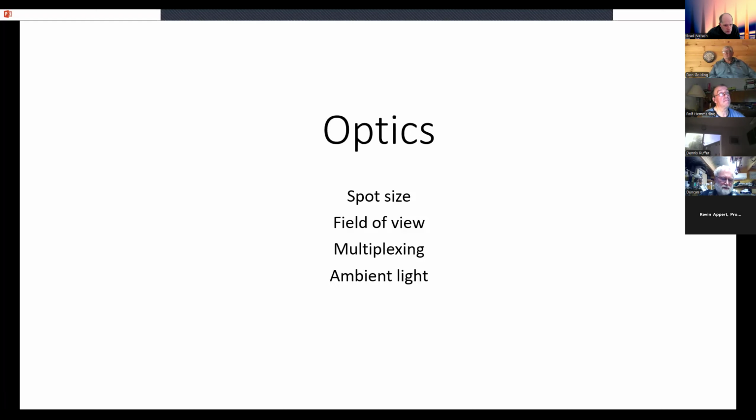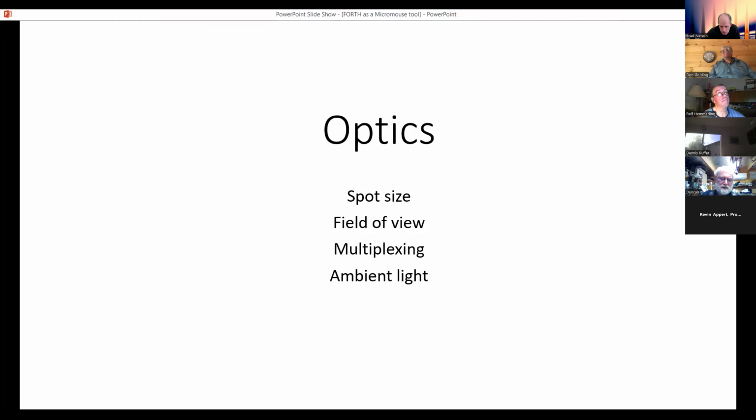There are lots of possible tricks with optics. You need small spots of light from the LEDs to make accurate measurements of wall edges, so you can make turns at the right place. Some people use lasers for this reason, but they're heavy and potentially dangerous. You need to ensure that the spot of light is visible by your sensors at all ranges. A wide field of view can be useful. This is on the sensors.